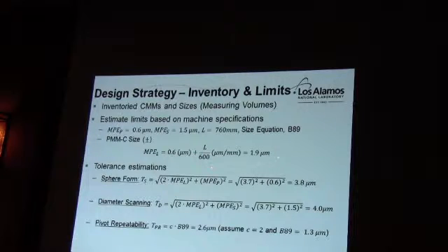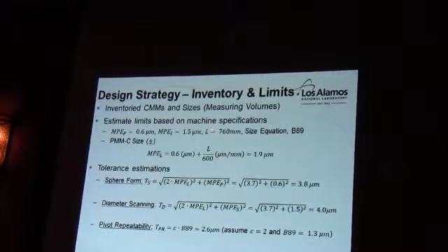This equation is pretty standard for any CMM that's calibrated. Here you're looking at the variance of your repeated measurement on the final dimension. Here is your length, your value, your diameter, your tolerance, your distance of your tolerance, your true position tolerance. Anything that's related to length is plugged in here. And this is what we call our length-dependent factor. When you plug this in and calculate it, you get your maximum permissible error for length in micrometers. This is all dependent on this L equation. All these equations differ per machine. The more accurate the machine, the smaller this variance number is going to be, and probably the smaller this number is. The larger the machine, the less accurate, the bigger.